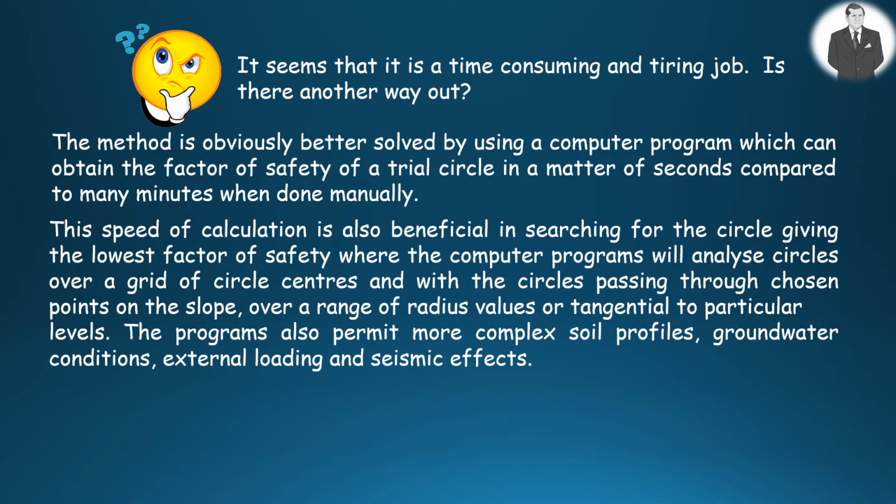This speed of calculation is also helpful in searching for the circle leading to the lowest factor of safety, where the computer programs will analyze circles over a grid of circle centers and with the circles passing through chosen points on the slope.